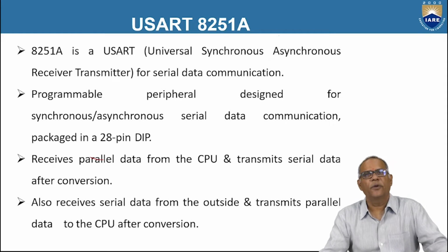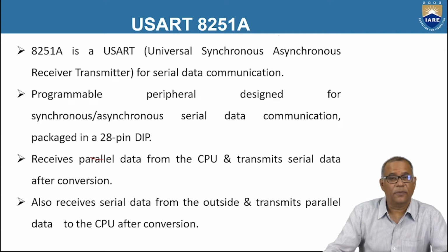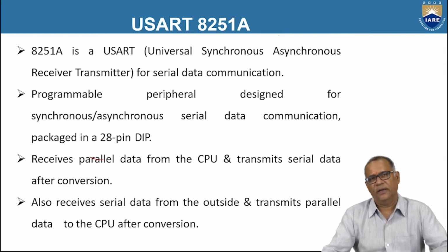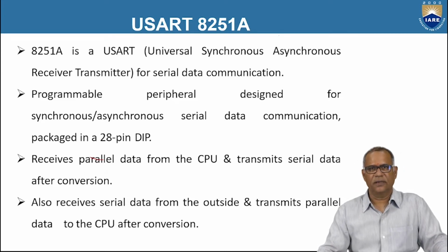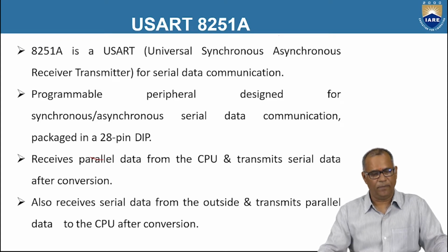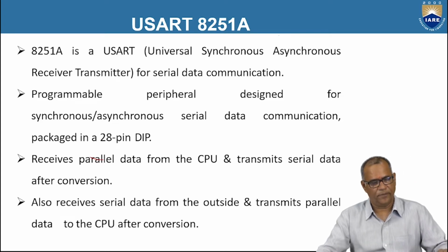As far as the speed of communication is concerned, it is very fast in synchronous communication, but the probability of errors is more in synchronous communication. So, to reduce errors, the characters are sent bit by bit, and a parity bit is also included in asynchronous communication. And in synchronous communication, both transmitter and receiver are synchronized by a common clock. So 8251A supports both synchronous communication as well as asynchronous communication.